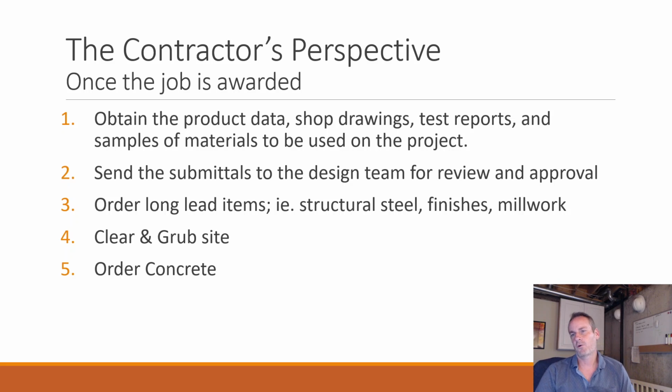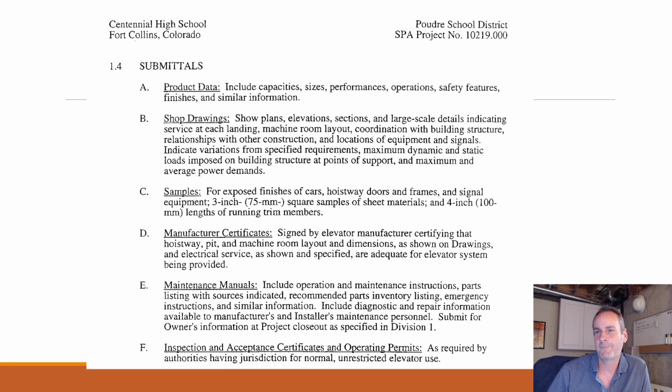Order long lead items, meaning it's going to take a while to get something in. You want to be ahead of the time. It's more of scheduling, making sure you're on top of what's coming up further down the line, and being aware of that. Start on the site as far as clearing it out, grubbing, which is like skimming the surface, getting the top surface. Order your concrete, get everything going. So this would be an example of